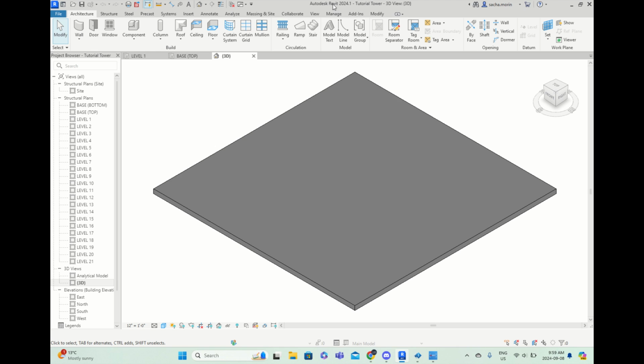just the same one as I showed you last tutorial. Again, my Revit is 2024, but hopefully that shouldn't be too much of an issue. And as I mentioned previously, we'll start at the plan view called base top, which is the top of your base plate. And we'll just use that to put our columns and nothing else. So let's go see how that works.